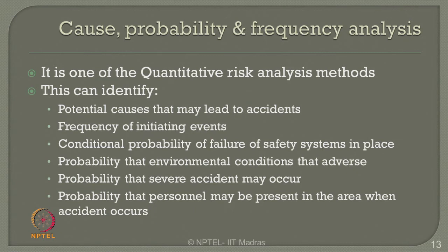All these are looked into in this kind of analysis, where the causes, the probability of occurrences and the frequency of such occurrences are all considered, which we together call CPF, cause, probability and frequency analysis, which is also one of the hazard analysis methods adopted in oil and gas plants.